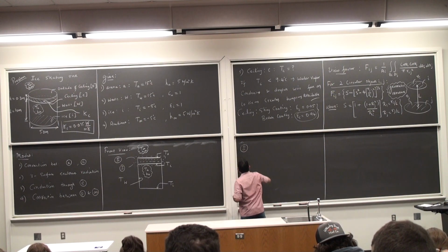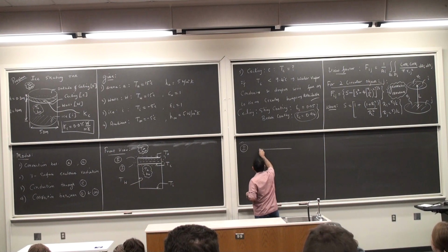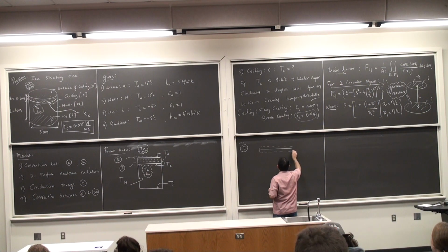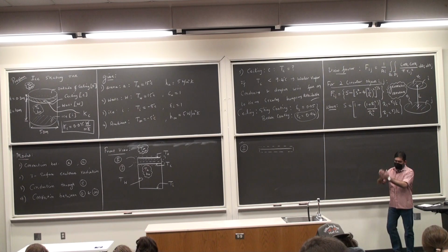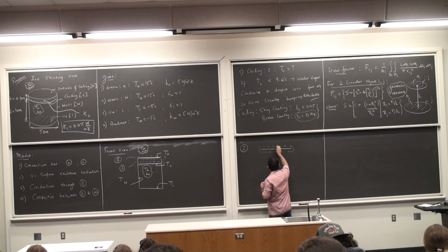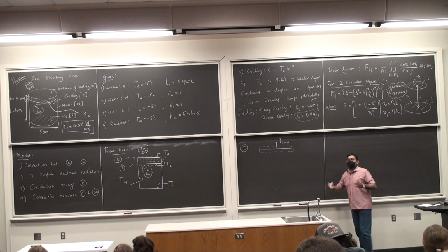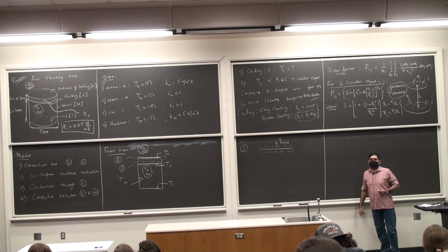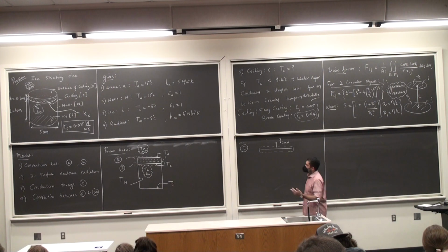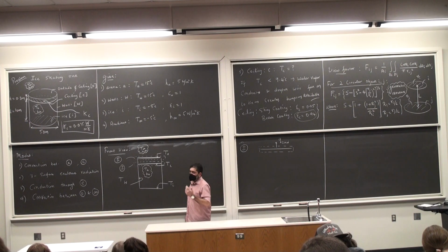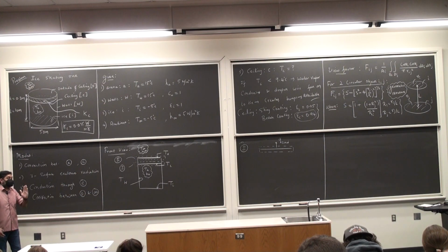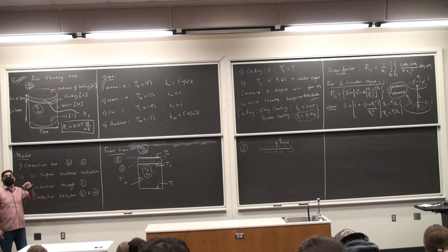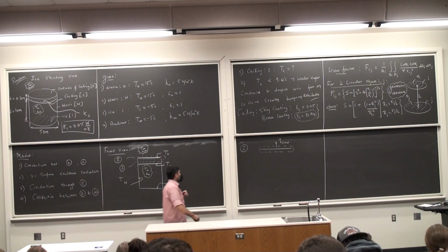So from 1, what are the modes of heat transfer? I'm going to have conduction taking place. So this is going to be Q conduction. I don't know the direction, I'm just drawing it up. Most probably I'm assuming that the ambient atmosphere is colder than the ceiling, so there is going to be convection from the top surface onto the ambient. If there is no heat generation, then the heat has to travel from C all the way to O. This is just an assumption.